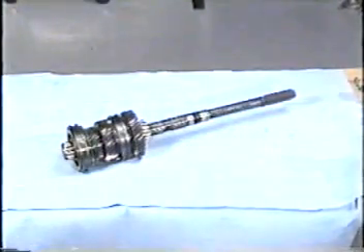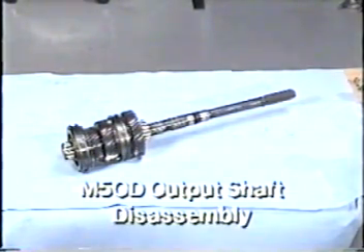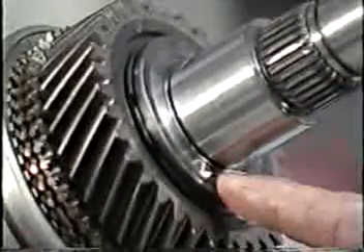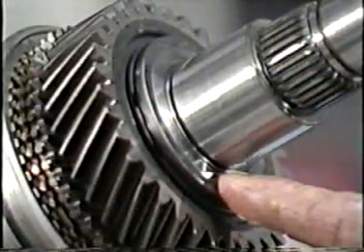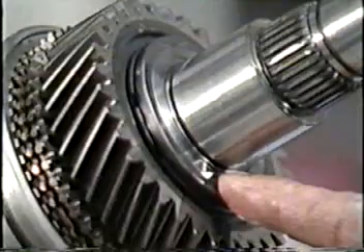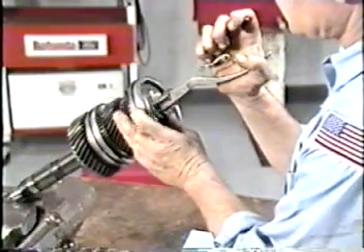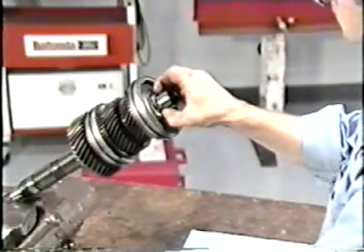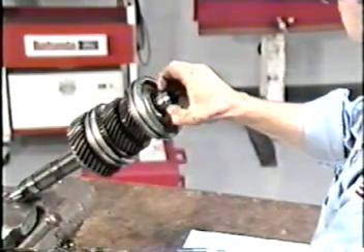In some cases, particularly synchronizers, you'll need to disassemble the components on the output shaft for closer inspection or replacement. We'll go through the steps involved in disassembling the output shaft on the M50D. The procedure is almost identical to the M5R2. The front flange separates the front or short side of the shaft from the rear or long side of the shaft. Use it as a reference point. You'll remove the components on the short side first: the output shaft pilot bearing, snap ring, needle bearing, and spacer.